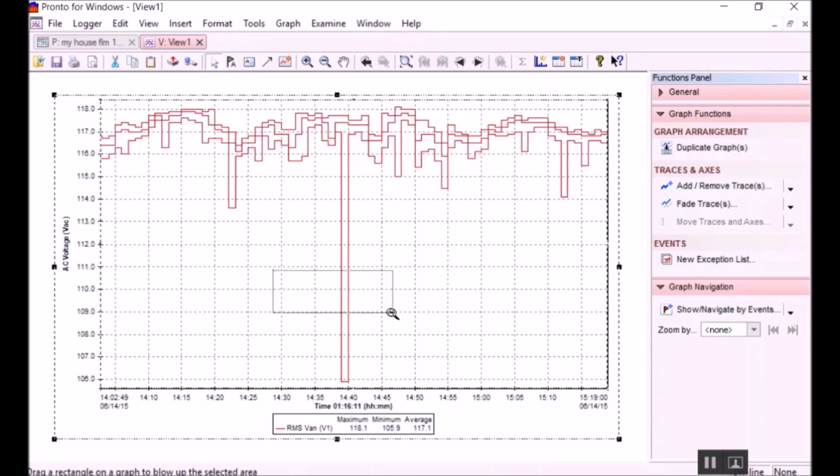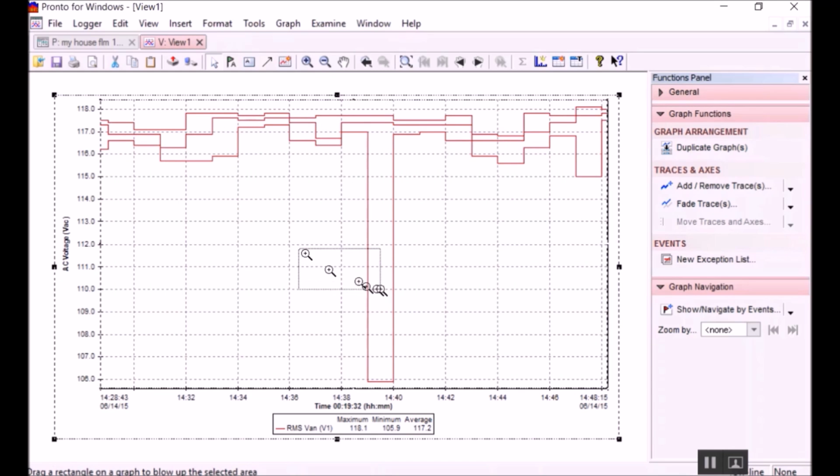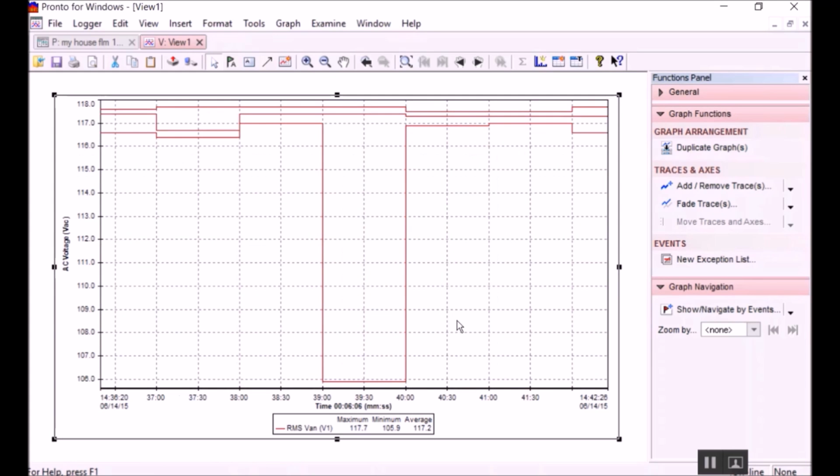And what you're looking at is an example of point or interval storage. Y lo que estás viendo son la gráfica de puntos de intervalos. Tiene unos intervalos de 1 minuto, de 30 segundos. So during each minute, it captures a 1 cycle maximum, a 1 cycle minimum, and the average of all the cycles.